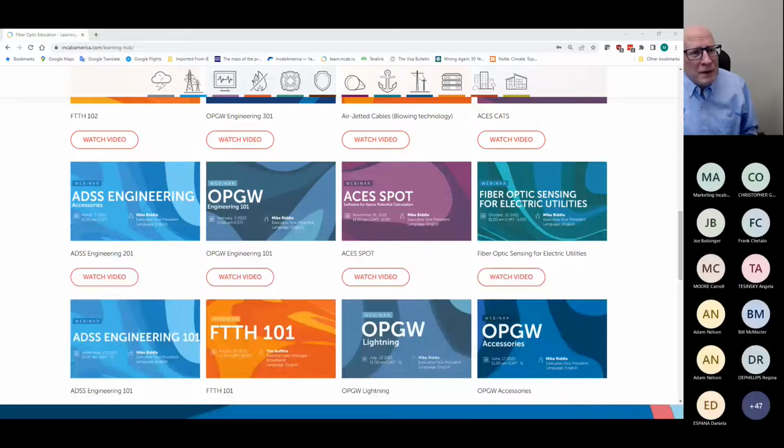And plus you would have to know, I mean, you can make a guess as to what it could be, but then how do you know in a service area what pollution you're actually getting? So there's not a hard connection there. So what I've said to people who've asked me that question is, if you're having problems with pollution on your insulators, then you're likely to have problems on your ADSS.